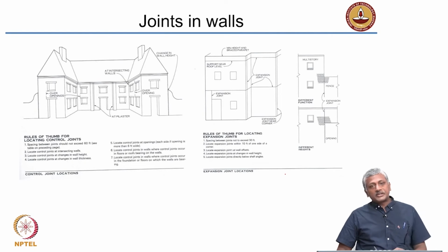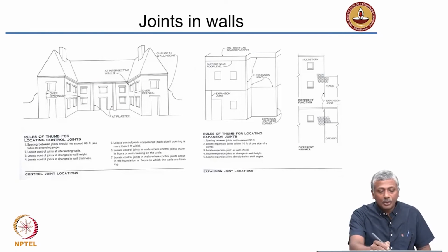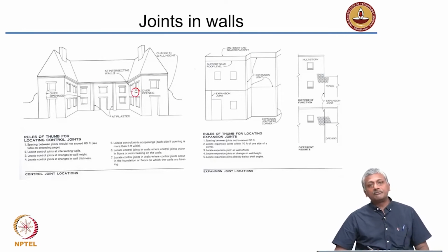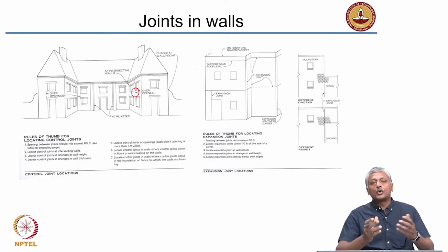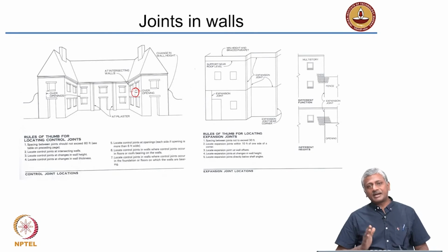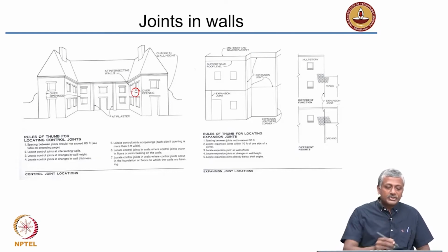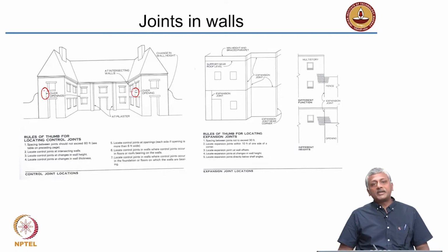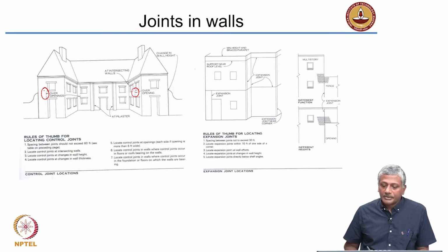Now, again the expansion joints are not only provided for running length, you may also want to provide it wherever you are seeing openings, wherever you are seeing window openings, because one of the common features you will observe when you see your own house, for instance, is that many of the cracks are emanating at corners and wherever the openings are there. So, to avoid such cracking and avoid failures, generally your joints may need to be provided over such regions. All you are simply doing is providing some free movement of the different structural components in your construction. Okay. So, those are some examples.